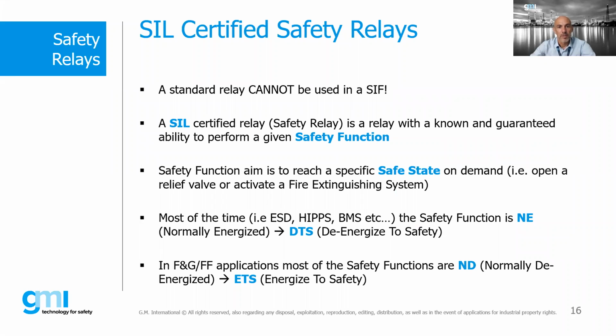So for a SIF, a standard relay cannot be used. You can't use a standard relay which is not certified for SIF applications. That is the most important thing we have to take into account.